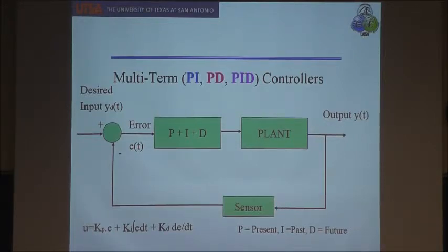So PID is a very powerful controller, and 90% of controllers in the world are PID type. Of course, if you don't worry about tracking, you can eliminate the integral part. PD is good to stabilize and to regulate any control system.